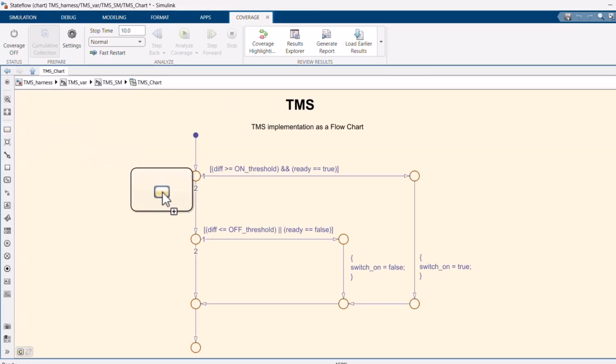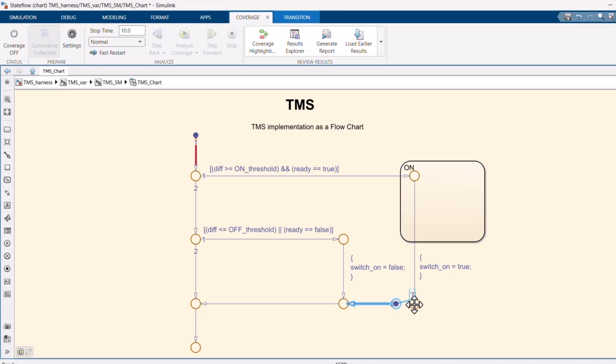And now we need a state object. Its name will be on. I use the capital letters for the state names. The condition action will be executed after entering the state. I might use the entry action, but I prefer the inner flow graphs because Stateflow animates the execution of it during simulation. I also connect the conditional transition to the on state.